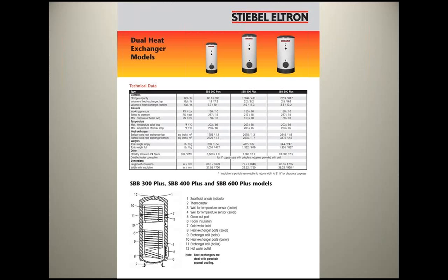I think approved in Oregon. This particular system, you have a heating unit here. This is where the solar hot water comes in. And this is a takeoff for space heating. So you have domestic hot water in the tank. This coil heats the water in the bottom. This coil takes hot water off to do radiant cores.